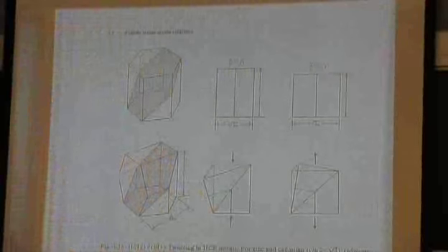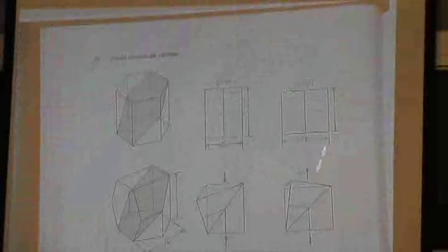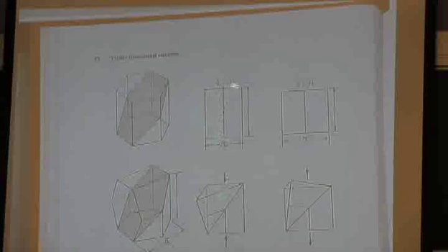And so what does this do? Most of these, and if I had had time this morning, I would have looked it up, most of the common metals that are BCC or that are HCP have a C over A ratio less than square root of 3, and that means that they will promote twinning in compression. Okay, promote twinning, that must be greater than square root of 3.